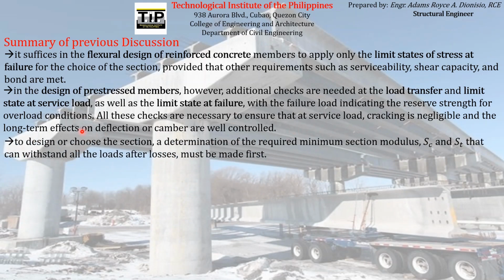And then last meeting, we also learned how to design a particular pre-stressed concrete member with respect to service load design. So to design or choose the section, a determination of the required minimum section modulus SC and ST that can withstand all the loads after losses must be made first.